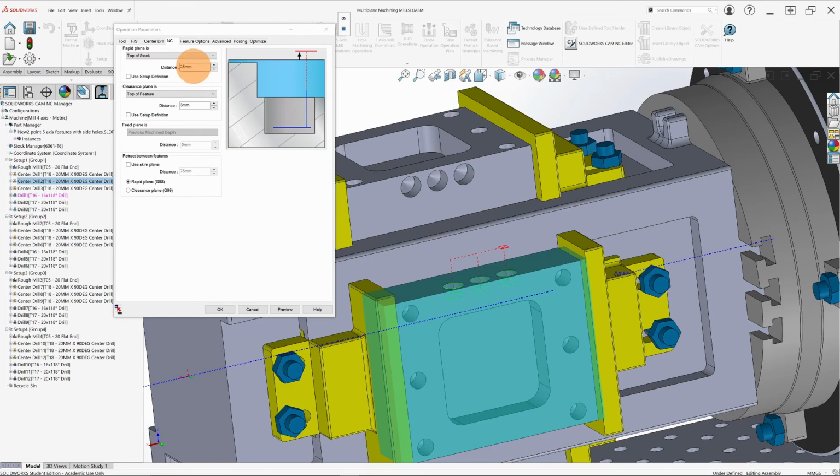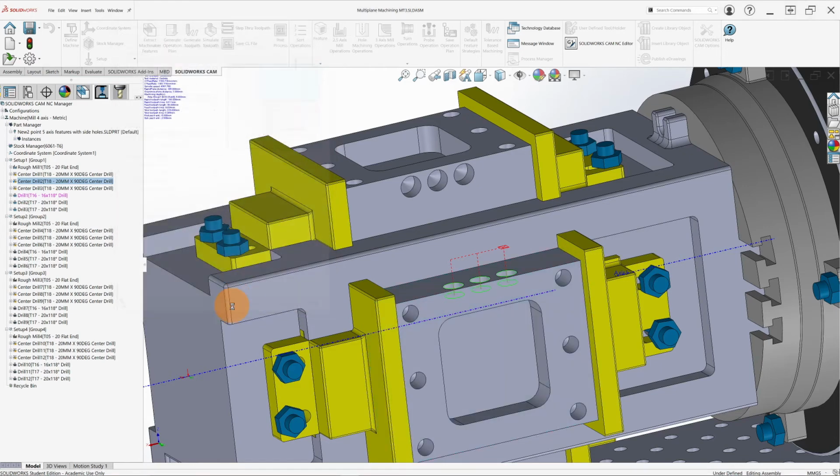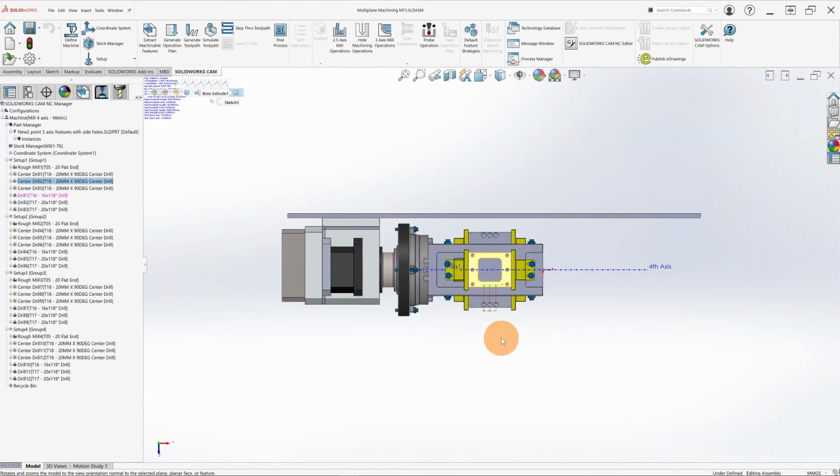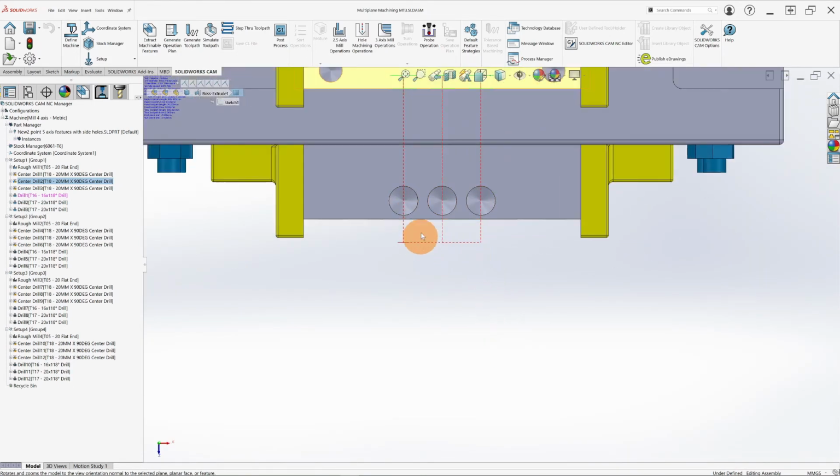So we want to change this to give it a safer height, and by measurement or whatever, I'm going to put that in as 105. If I press OK there, now you can see the height. I'm just going to look at this plane, so I'm going to click here and look normal too, and you can see that gives me enough clearance.